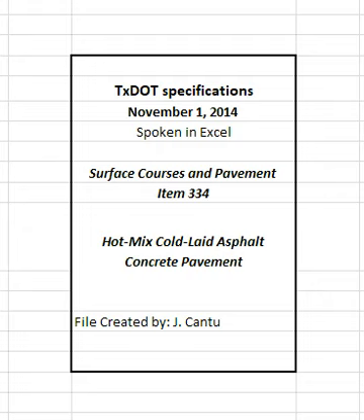4.8 Ride quality. Use surface test type A to evaluate ride quality in accordance with item 585, ride quality for pavement surfaces, unless otherwise shown on the plans. 5. Measurement. This item will be measured by the ton of composite asphalt concrete mixture of the type used in the completed and accepted work. Measure the weight on scales in accordance with item 520, weighing and measuring equipment.